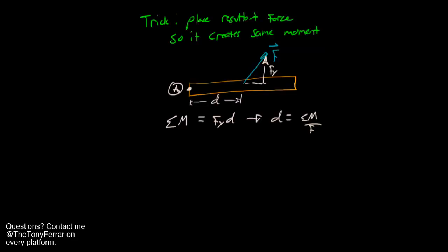The reason I say there's an infinite number of options is the second we move it, if we put F here instead, now we have two unknowns. We have a vertical distance and a horizontal distance, and you could do that. R cross F, we could solve that, and we could do it again that way. Usually it's easier to pick and lock ourselves down in one direction and not the other. But this is a great little trick so that instead of having to have an applied moment, we can just pick a location, put the resultant force, and it has the overall same effect on the system as all those individual forces, including the moments that they caused.